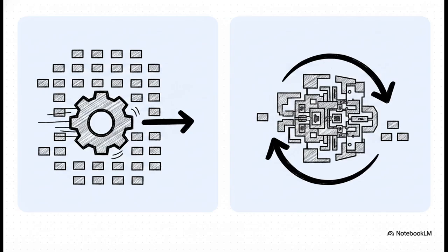Because the commands are so simple, RISC architectures need more general-purpose registers to juggle temporary data. On the flip side, we have CISC, or Complex Instruction Set Computer. CISC uses a large, complex set of variable-length instructions, meaning one single instruction might execute a whole multi-step operation.